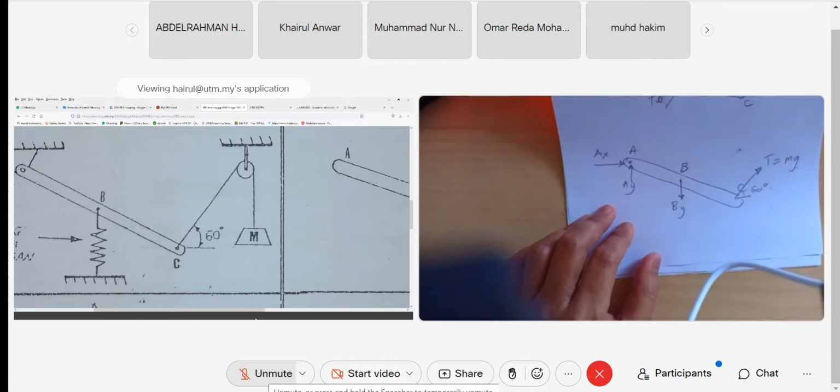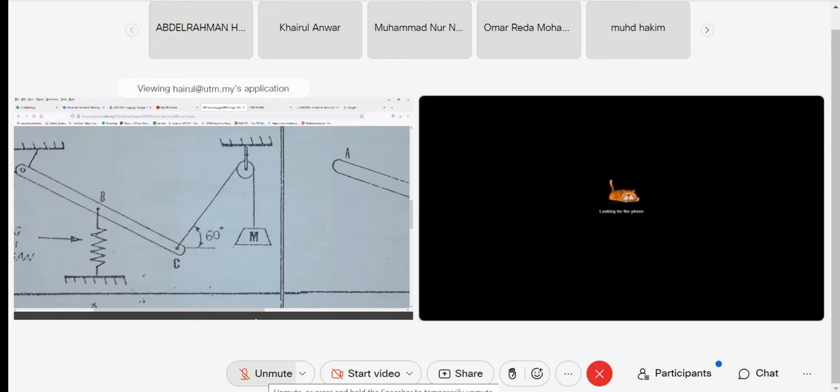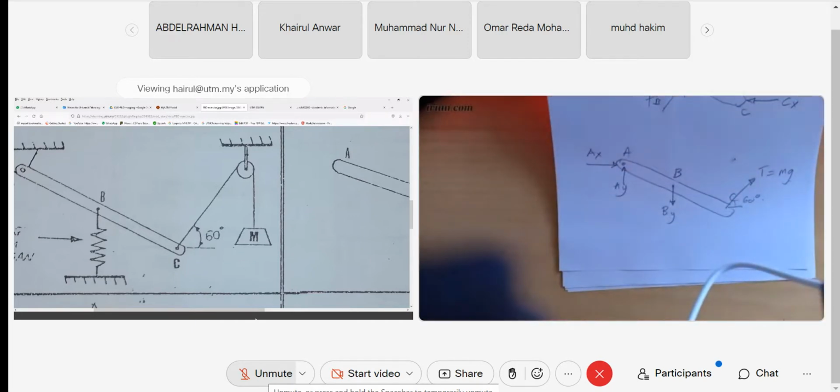SY. You can use SY if the material is ductile. What material do you use? Cast iron, steel, aluminium, silicon. So you look at the yield strength value from the table of properties. Then the safety factor is the yield strength over the stress, for whichever one is critical. You identify in this member ABC which one is critical. So that means your component is safe. You have to identify which component along ABC is critical.